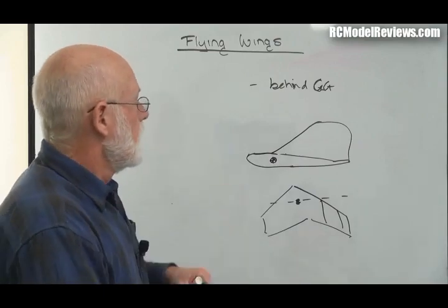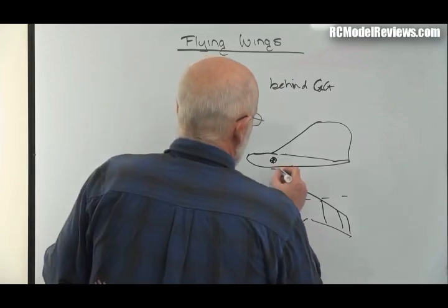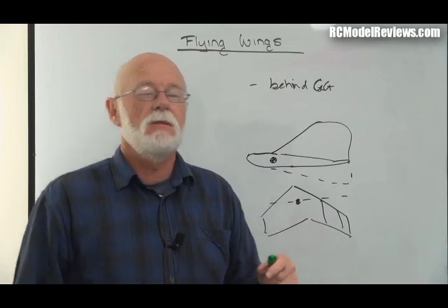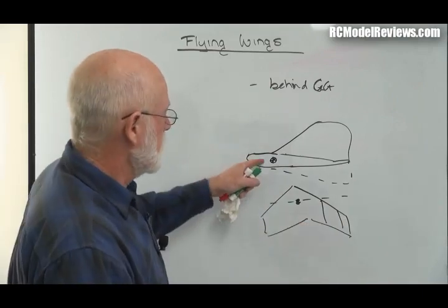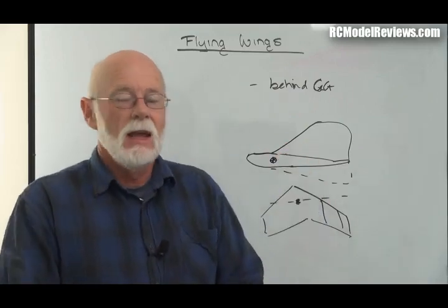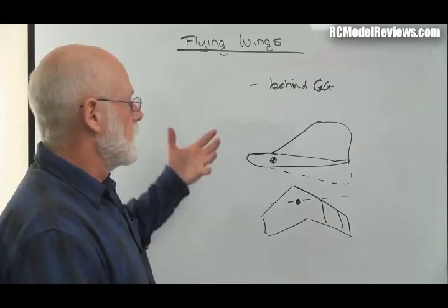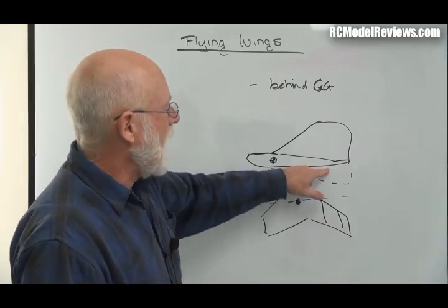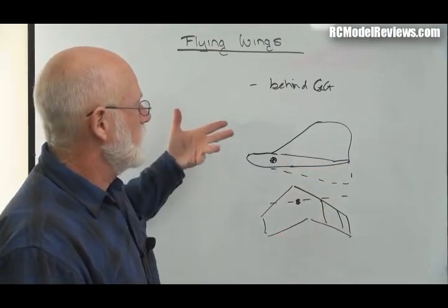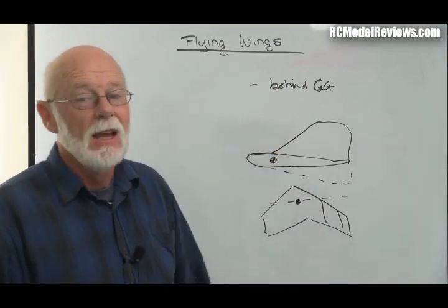Well worth considering. So the other thing is, if you're working with tip fins, if this is a tip fin, do you want any area under here? A lot of planes have area under there. The Tech 1 FPV 900 I'm putting together at the moment has tip fins that go above and below the centre line of the wing. Now, from a practical perspective, having tip area below the tip of the wing is just asking for it to get smashed off when you land. But from an aerodynamic perspective, there are certain benefits. It's going to reduce the tip vortex even more. So there are some real benefits to having some below the wing centerline, below the bottom of the aerofoil. So yeah, it's all compromises.